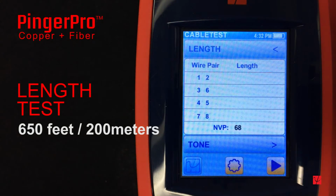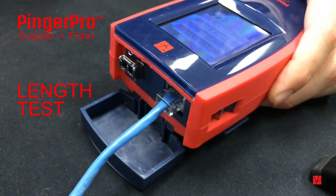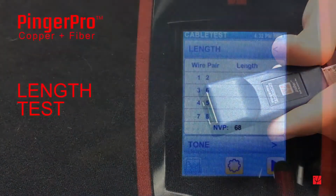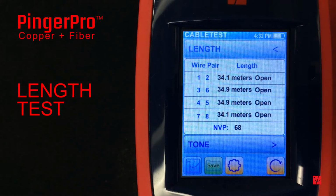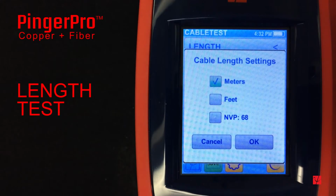From the WIREMAP screen, press the length button to go to the length test screen. Attach an Ethernet cable to the PingerPro. Make sure that the far end of the cable under test is not connected to the terminator or any device. Press the play button to run the test. By selecting the settings button, you are given the option to select either meters or feet for the length measurement.